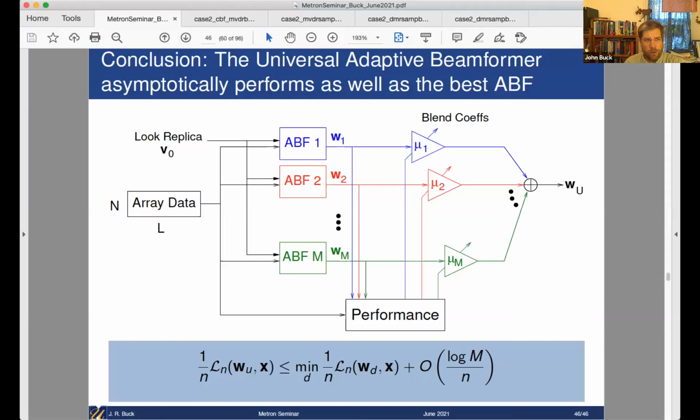The other useful news about that, to people that aren't used to thinking about this, is that everything I'm talking about here is for one look direction. I would be doing this in parallel for every beam in my passive sonar system, but they can all share the eigenvalue decomposition. So the largest fixed complexity can be shared across all the beams and all the branches.